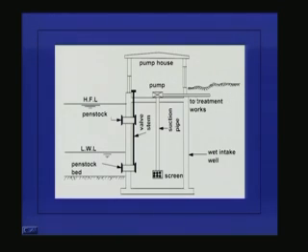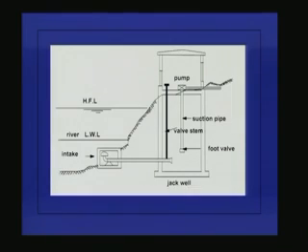So, this is a wet intake well system for a river intake. We see the next type of river intake. This is called a jack well, and here we keep the pump house not inside the river, but away from the river on the banks, not too far away, but slightly away from the banks.